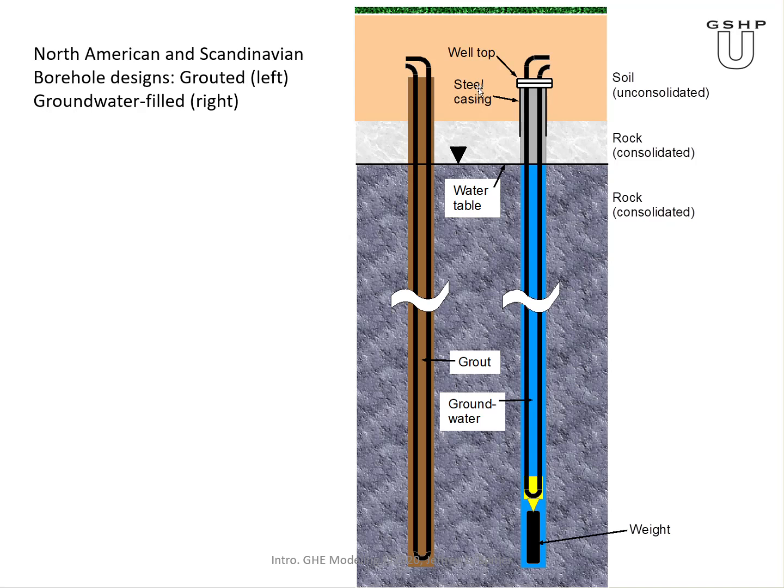And what you see here is the borehole, this sort of dark brown, has been drilled in. You see it's covered over with soil. That's correct. So typically it's drilled, the tubes are left sticking out of the ground, and someone comes in and does some trenching and connects the tubes below ground. That's why I've got it shown like this.